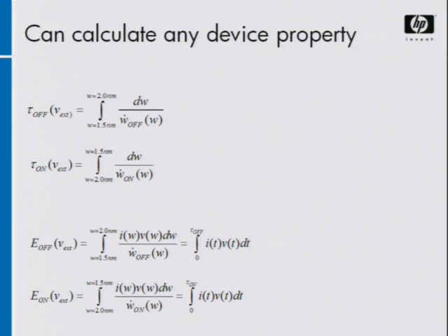So we can calculate all of this, and we can do measurements, and we compare measurements and calculations. And essentially what we see is that for our smallish devices, for devices that we make which are intentionally 50 nanometers or so, we can switch these devices in roughly a nanosecond, a few nanoseconds, and the switching energy is a few picojoules. That's essentially nothing. That's as good as you need to be, just because the circuitry that you connect things up to are going to be slower than that and dissipate more energy than that.